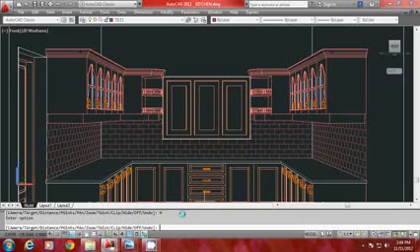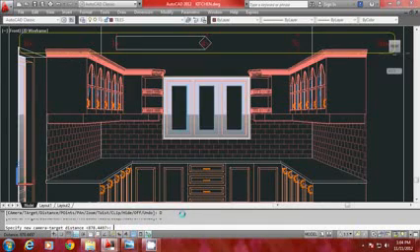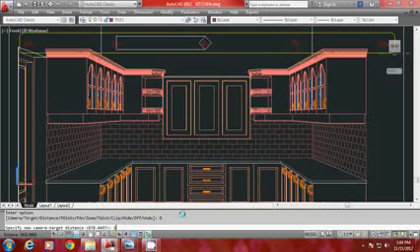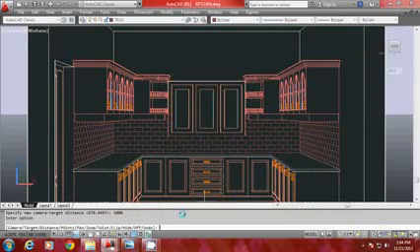So now you have so many options. You can either change the distance of the camera if you want, or you can change the focal length of the camera. Now I would like to change the distance slightly. So I'll go to the distance option again, and it will show you the current distance as 878. I'll give a higher value, let it be say 1000 units. So the camera is moved slightly backwards.